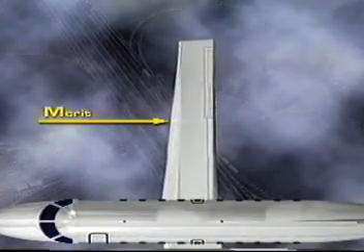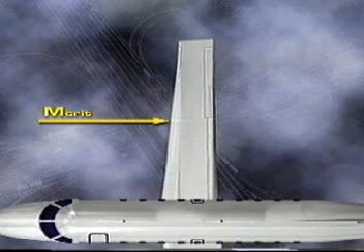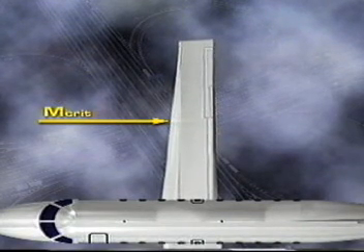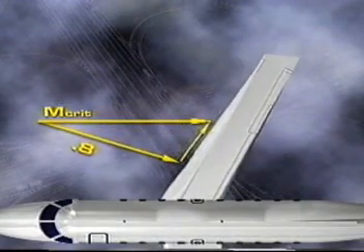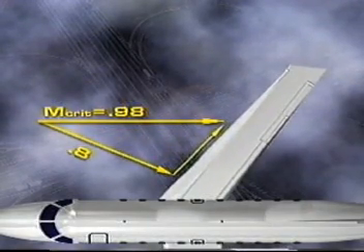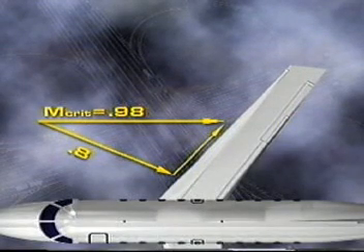All is done to make the wing believe it is flying slower than it really is. Let's remember how, in a straight wing, airflow through the wing is really perpendicular to the leading edge. By sweeping a wing instead, the velocity vector has two components, one perpendicular to the leading edge and the other parallel to the leading edge.